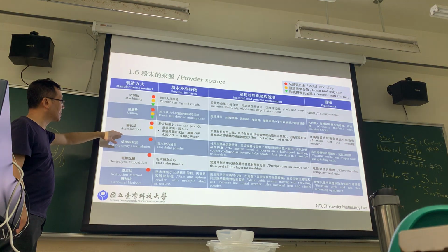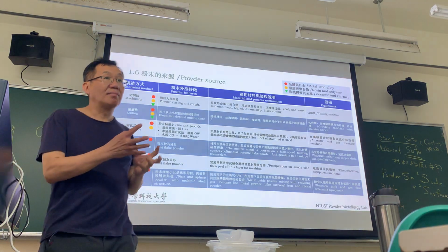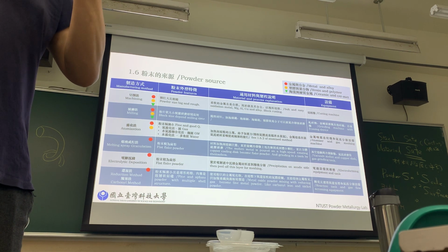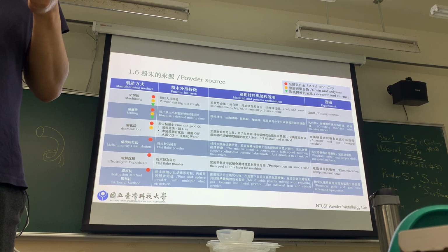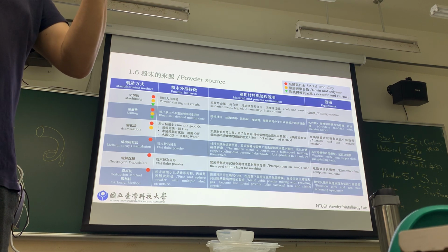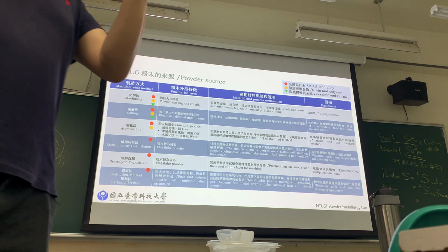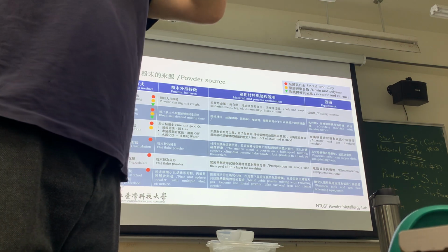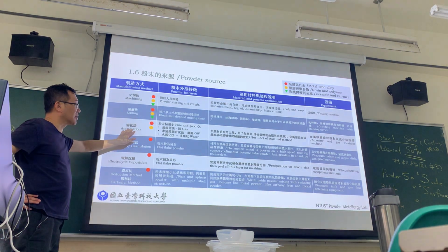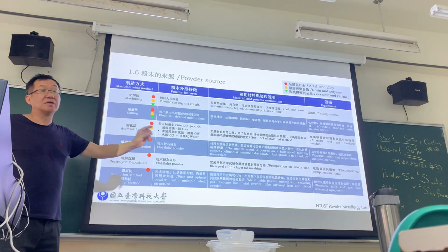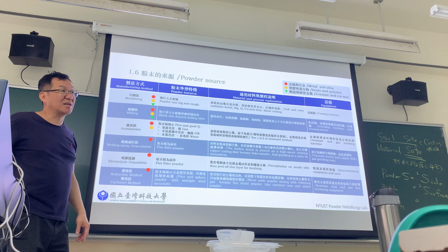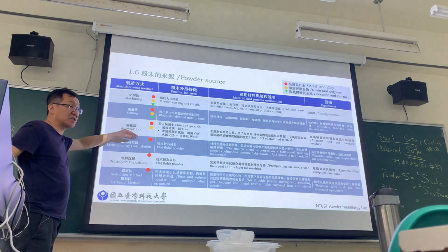Number 3 is atomization. Atomization is melting the materials like soup, steel soup, stainless soup. Then spray, like using spray water for your flowers or plants. The pressure and the liquid go through the pressure atomization and make small particles. This is popular in MIM and metal AM, but PM doesn't use this one, because the particle size is very small, smaller than 70 micron, maybe less than 50 or 60.